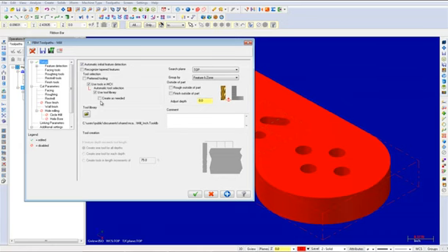Use tools in MCX looks in the current Mastercam file for an appropriate tool. Use tool library searches the selected tool library for the necessary tools. Create as needed creates the necessary tools using the tool creation parameters you define. Search plane detects only features that can be machined in the selected plane. Group by controls the organization of FBM Mill generated toolpaths. Feature and zone: Mastercam creates a separate subgroup in the toolpath manager for each zone. And finally, minimize tool changes is where Mastercam sorts the toolpaths into subgroups.